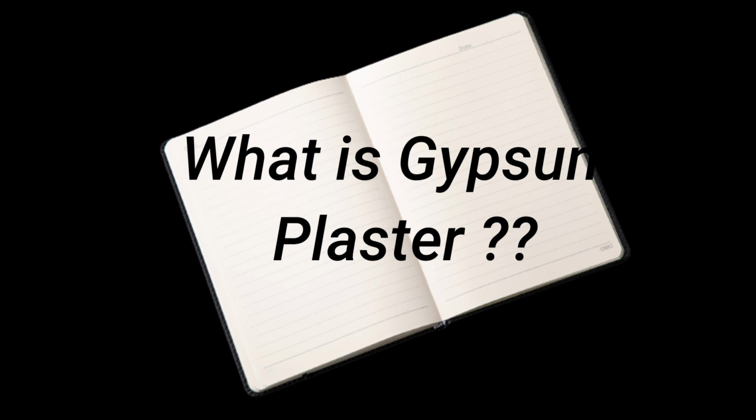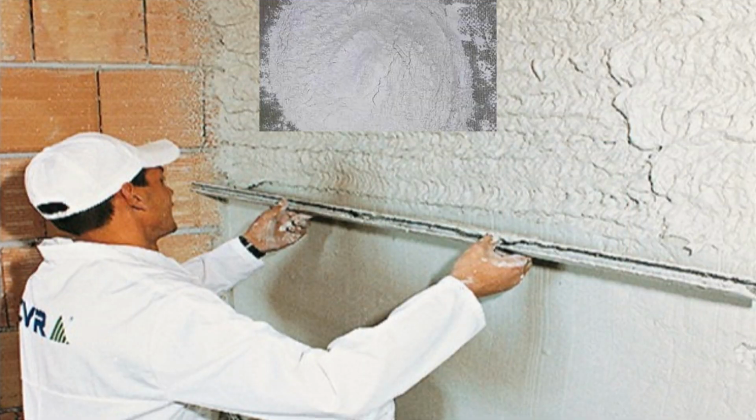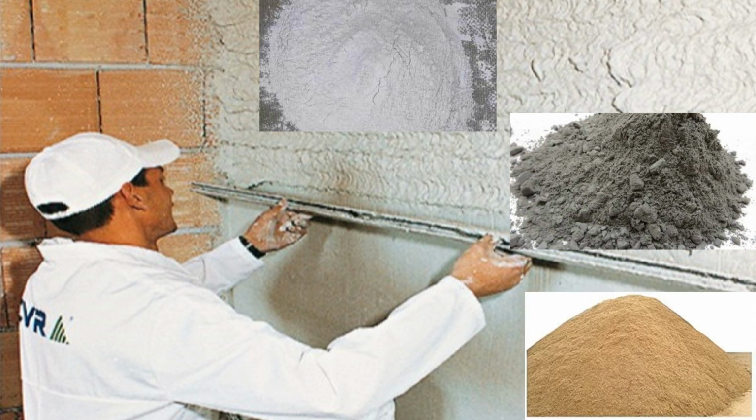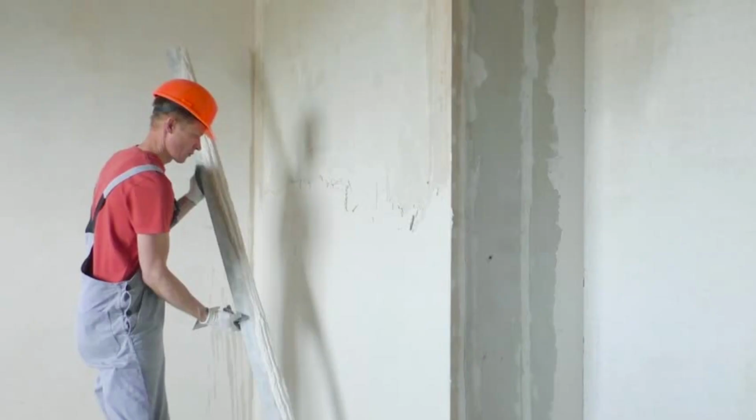Next, let's see what is gypsum plaster. Gypsum is used in gypsum plaster as a binding material instead of cement. When dry powder gypsum is mixed with water, it becomes hard. It is available in ready-to-use format and does not require sand. Gypsum plaster provides a smooth interior finish, which is an ideal base for good quality wallpaper and paints. It can be applied on both rough and smooth surfaces of the wall.